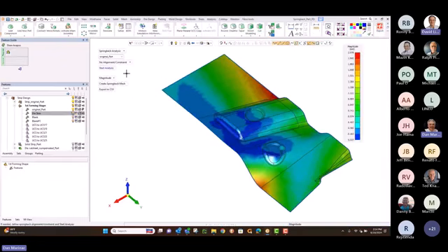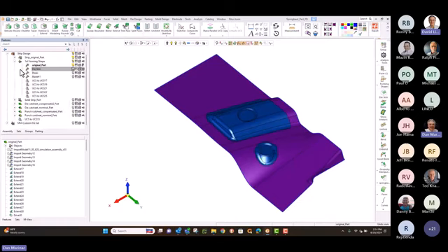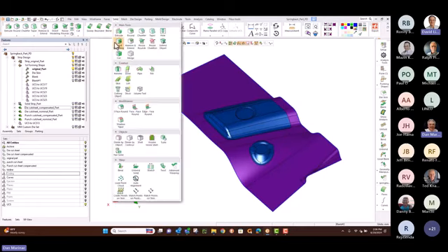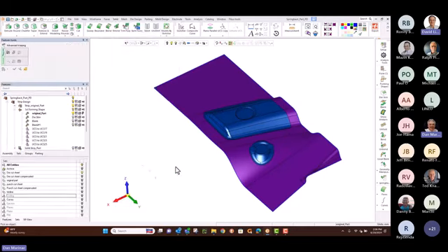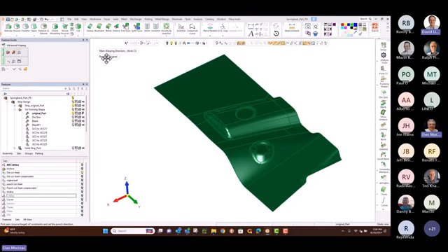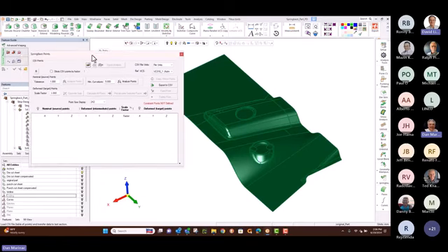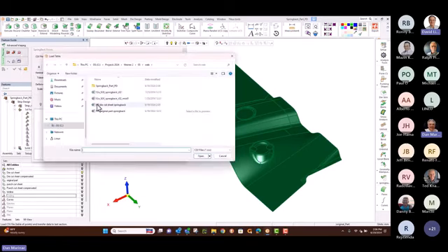Now, as we said, this is an important thing to have in quoting, perhaps looking at the part like that example Dan just showed you. But here in tool making, it's also critical. I want to apply this to the tool and leave the strip itself as nominal. So taking the information we have now, we're going into our warping utilities here. We can keep the original, that way we can see what has been warped as compared to what nominal would look like. And we'll pull in that CSV file now that we just created.